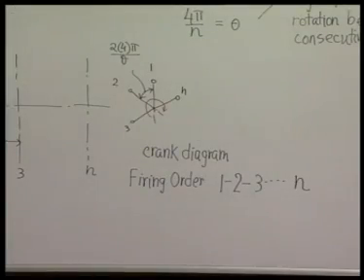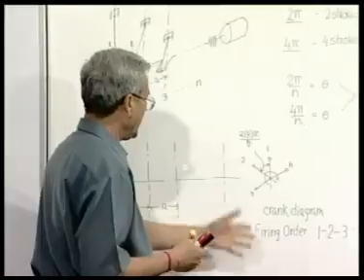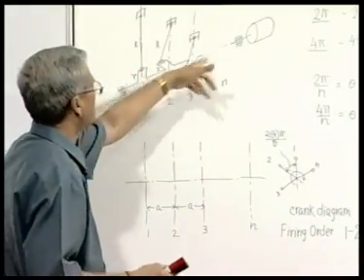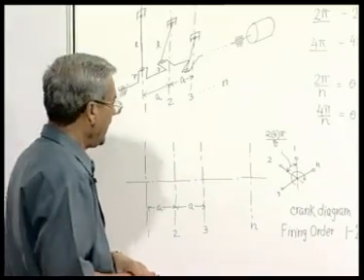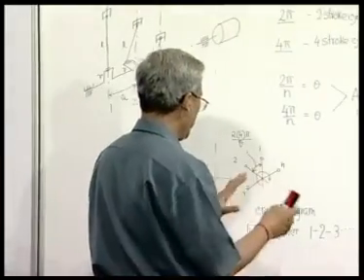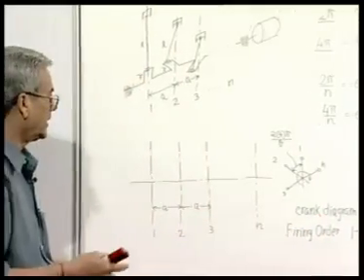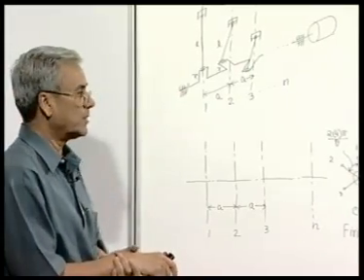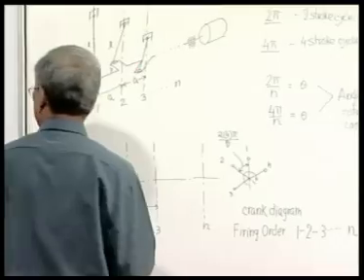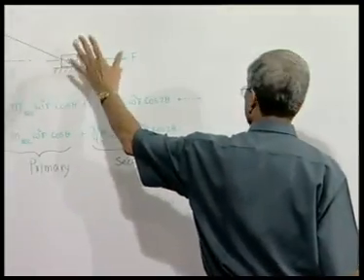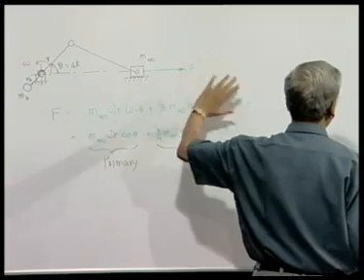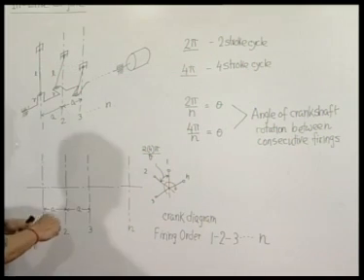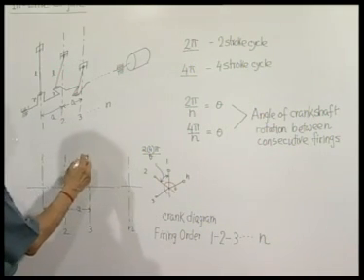Now you will see, as we will just now find out, that this firing order is very important, because according to that only the crank locations will be arranged, and the same engine with a different firing order and different crank settings can behave differently from the point of view of balancing of its forces and moments. Now, in case of a single slider crank system or single cylinder system, there was only a matter of force, but now what we will have? We will also have a moment, because force is acting at different lines, and therefore,